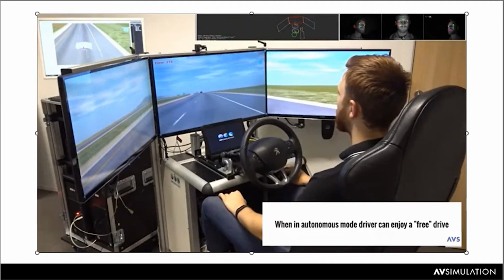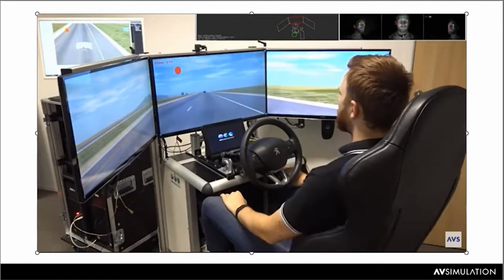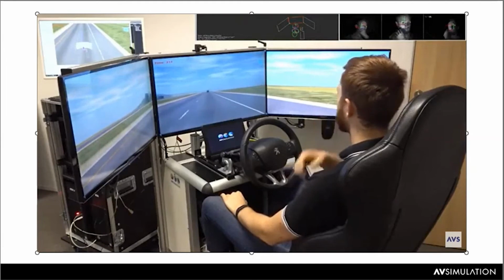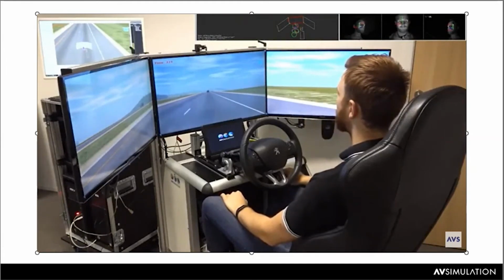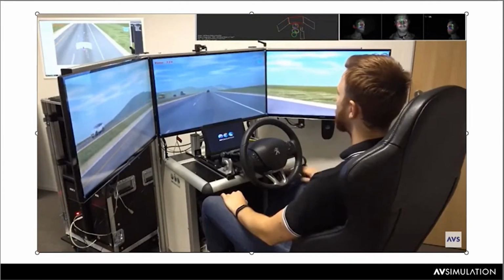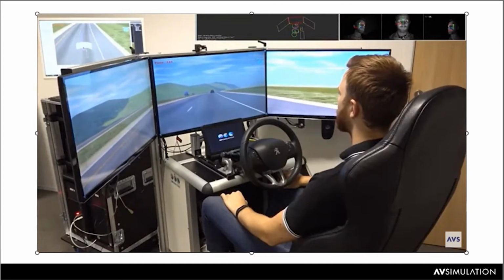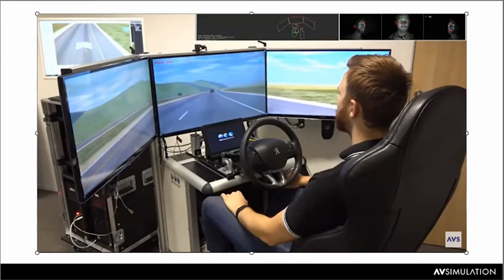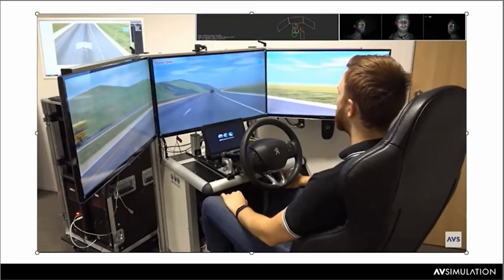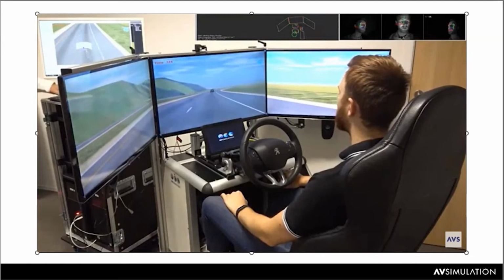So I just enabled the autonomous mode. We binded it to a key. It's very easy to bind the different events to the keyboard or X inputs or any USB device. Even from UDP packets, you can trigger events. And so for my finger, for instance, we actually use the keyboard controller. We took it from an old keyboard and mapped my finger to one of the keys of the keyboard, and that's how you can create these human factor use cases, proof of concepts with very cheap budgets and very efficiently too.